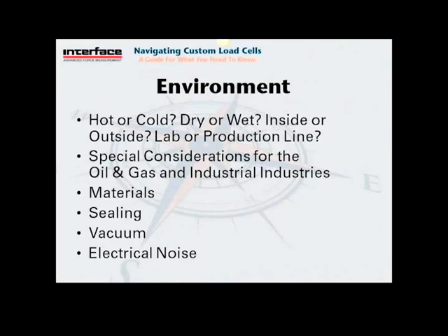The environment is how hot or cold it needs to be. Our standard low profile has an operating range of -65 to 200 degrees Fahrenheit. You also need to think about if it's going to be a dry environment or if it's going to have high humidity in the area or if it's going to be in a wet environment, which may also be submerged.